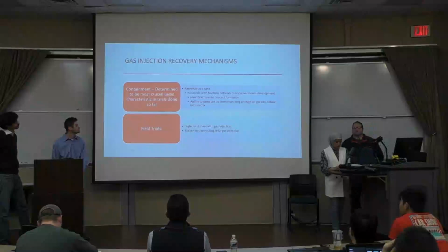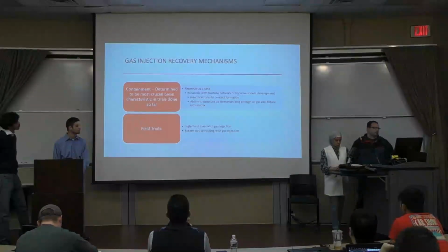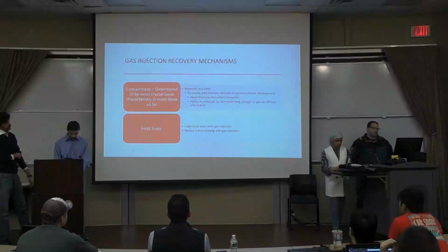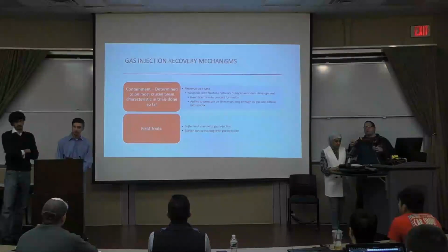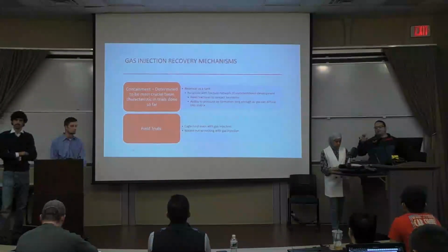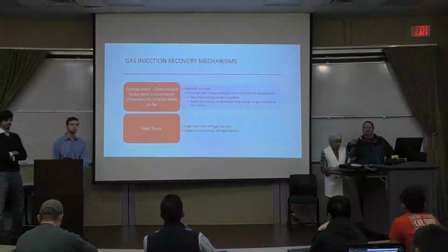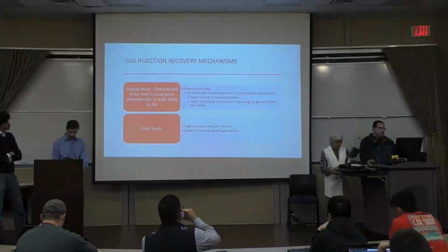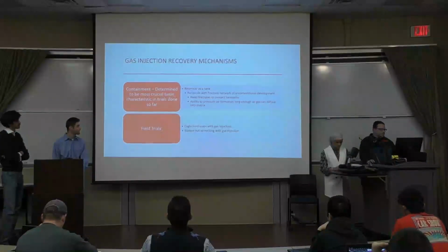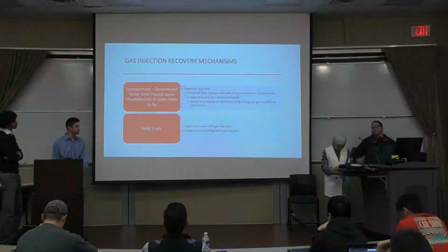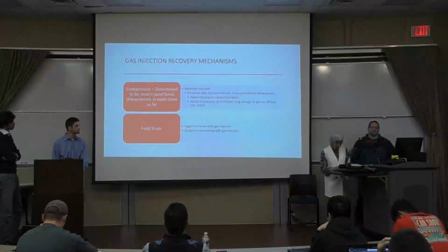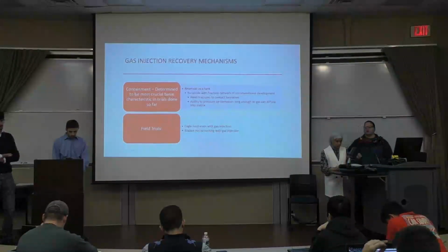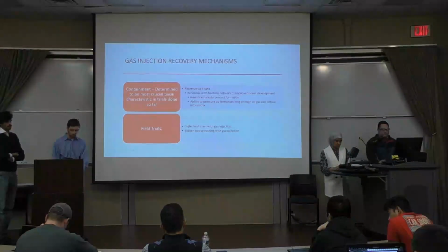Containment is another important recovery mechanism, and we need to think of the reservoir as a tank. However, we need to reconcile the fact that we use the existing fracture network to displace our gas with increased contact area. However, we need to pressure up the reservoir so we can get above our MMP. So there's a trade-off. There have been some field trials. For instance, in the Eagle Ford, gas injection has worked really well, and it's been a total failure so far in the Bakken. What they're alluding to is they think containment is an important determining factor of success or failure.